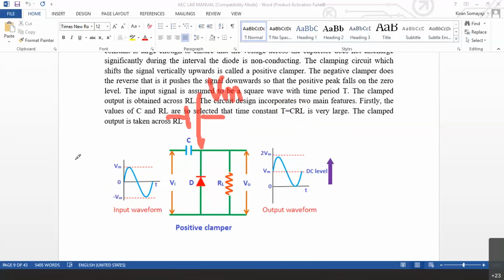It is Vm. That means, let us say if this is plus 10 and if this is minus 10. Now here, as this is plus side, when the diode is conducting, this way current is flowing. So when this way current is flowing, naturally this is plus side and this is minus side. That is how capacitor can be represented like a battery now. Now, because the capacitor remains permanently charged, capacitor is giving additional plus 10 volts to the output now. It is as if we are connecting an AC source in series with the DC source. There is this AC source, there is this DC source.